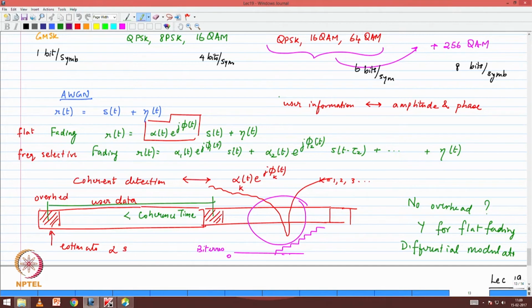After the class, several students stopped by and asked, you have a channel estimation happening whenever there is a training scheme, so basically there is an estimation that is happening here, an estimation that is happening here. This is less than coherence time. So why is the channel changing within the coherence time? So let me elaborate a little bit more.